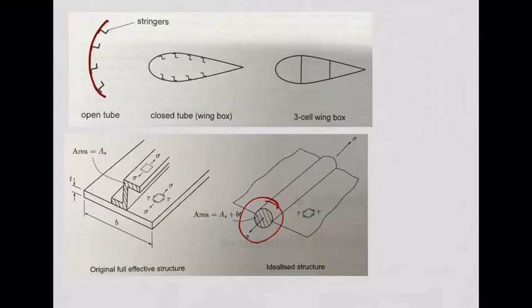And then, in bending, you have the neutral axis. Below, you can have tensile stresses, and above, you can have compressive stresses, or vice versa. Remember that from bending? So if you think of this very thin skin under the effect of compressive stresses, if you don't have anything else there, the skin will buckle, right? Agree with me?